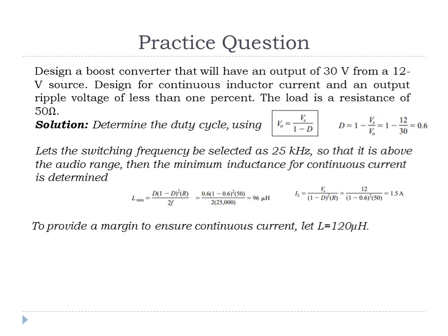Let us say L equals 120 microhenry. If we select L equals 120 microhenry, then what is I minimum? It can be calculated by first finding delta IL upon 2, which is 1.2, using all the values, and particularly L taken as 120 microhenry. So I minimum is 1.5 minus 1.2, which is 0.3, and it is above the zero level.